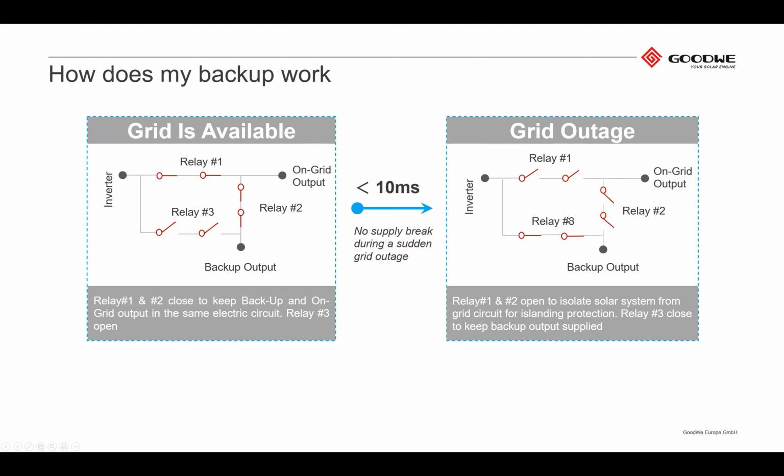But these relays will react also based on the inverter capacity. So the relays are a limiting factor. Some devices might have what they call a bypass relay that essentially eliminates a lot of this when the grid is available, so that you can draw a much higher capacity from your backup when the grid's available. Our inverters, unfortunately, do not have that.